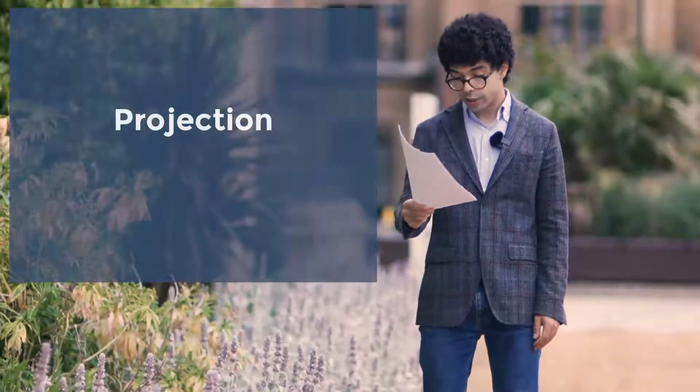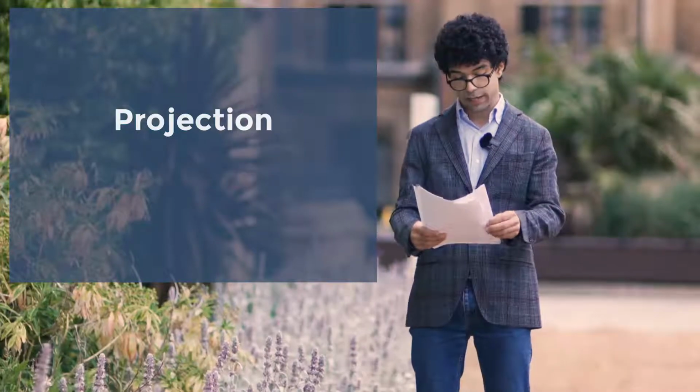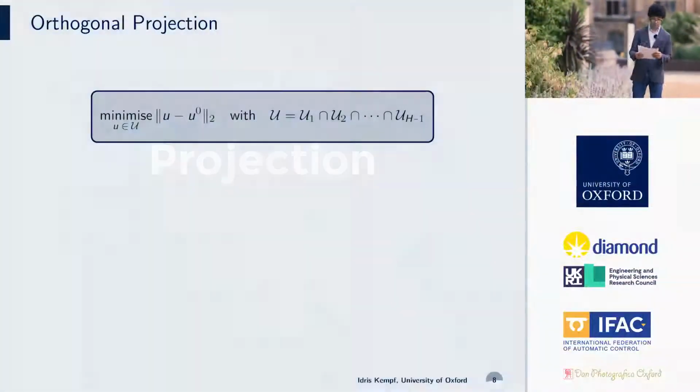The orthogonal projection onto the input slew rate and amplitude constraint set that is required for the application of the fast gradient method. The orthogonal projection itself defines a constrained quadratic program. Recall that set calligraphic U represents the input rate and amplitude constraint set, and that sets calligraphic U_k represent 2 grouped amplitude constraints and 1 rate constraint that affect elements u_k and u_{k-1} of the vector.